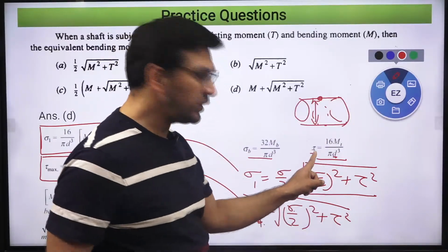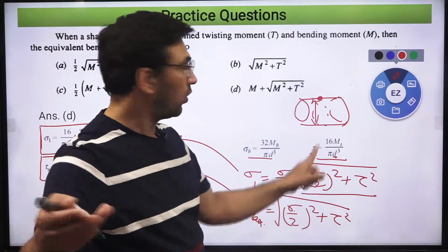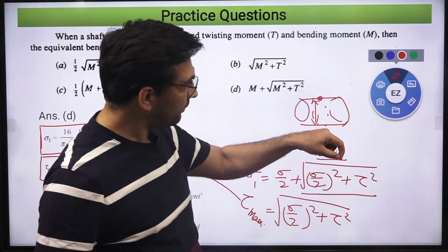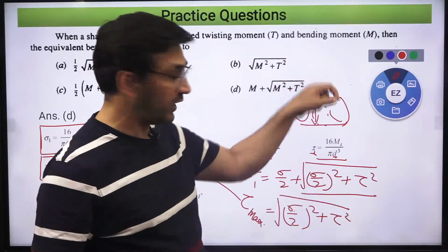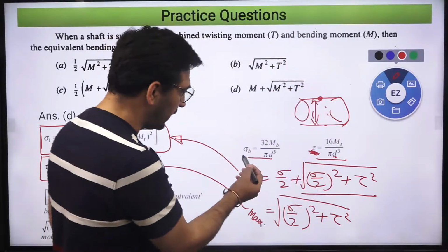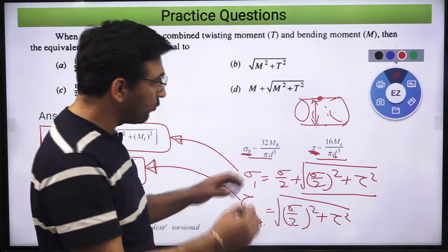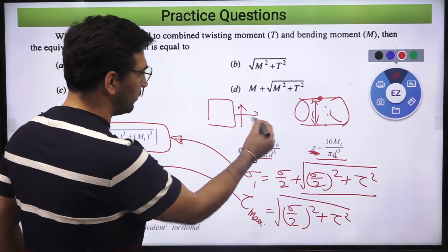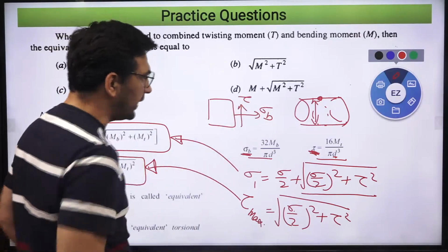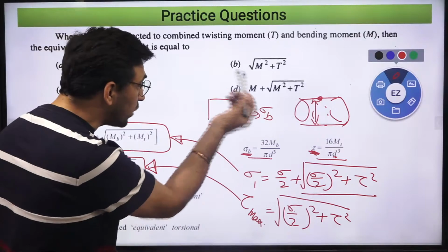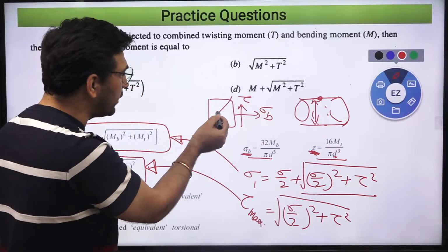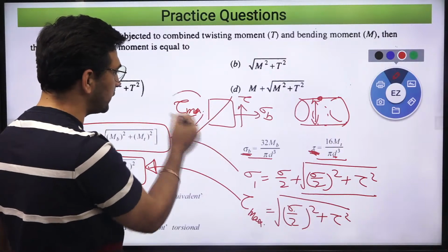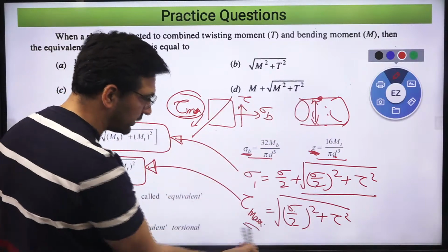So this also is the maximum value of the shear stress on the shaft, at any point on the periphery. But if I take any element on that periphery in which you are applying this maximum value of shear stress and this maximum value of bending moment, then there is going to be some plane inside this material where you have the maximum value of the shear stress. And that maximum value of the shear stress in the element that I have taken on the surface is this one.